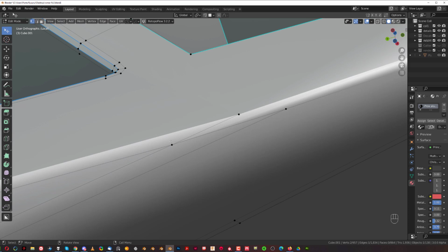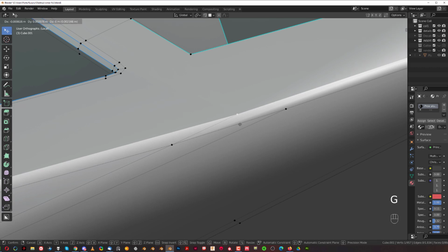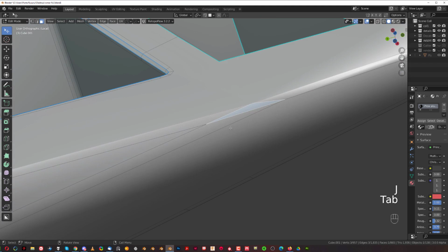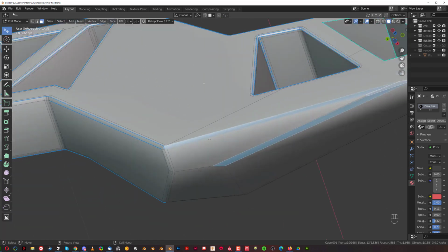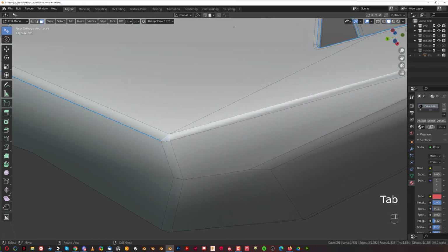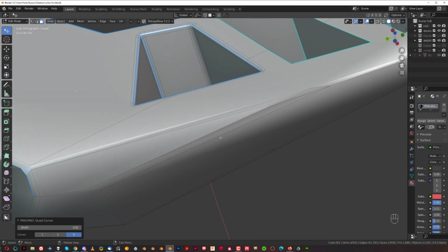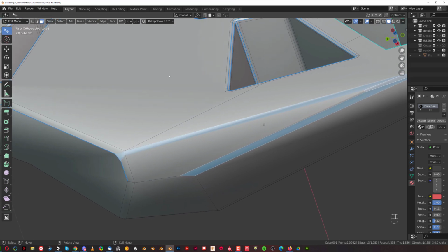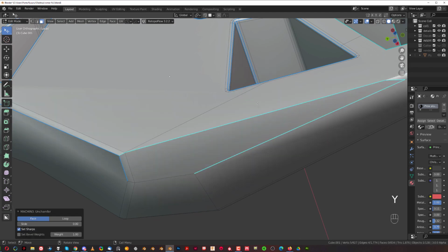Oh. We will need a quad in here, so let's slide it back. But if I do that, I think the angle's gonna shift. So we could just do this, J, and then convert it to a quad. I wonder if it's gonna work. So let's go quad. I think it did work, yeah. And it redirected it this way, which is perfect. So let's remove this edge now, and let's quad this one the other way. So we're gonna quad it this way, so it's gonna flow along this edge, and we're going to select this one and Y and unchamfer. Perfect.